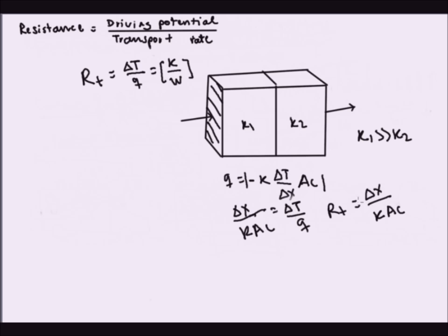From this equation you can see that the thermal resistance is linearly proportional to the length of the wall. So the resistance will increase as this length increases, sort of as the example that Servio says a lot in class: imagine you're trying to run out of a building that's on fire, and imagine how easy it would be to leave a building that is very short, and you're three steps away from the entrance rather than 50 steps away. The resistance to leave a building would be lower if the length is lower.